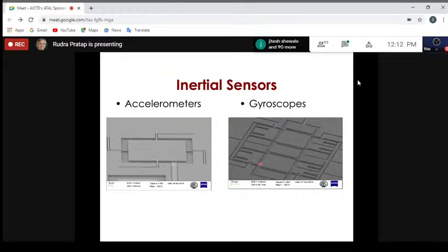A little bit more complicated structure will be this gyroscope, which has two proof masses. It has a comb drive here, comb drive here. This is a big plate you can see here. This is a plate with comb drives. This is another plate, but this plate is a fixed plate with comb drives. This is another, just a replica of this proof mass here, and that also has comb drives.